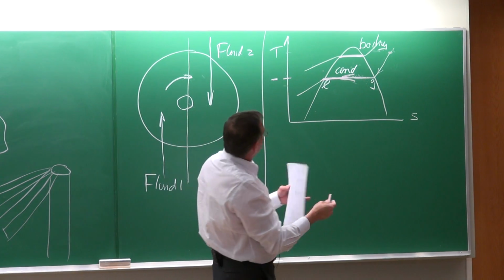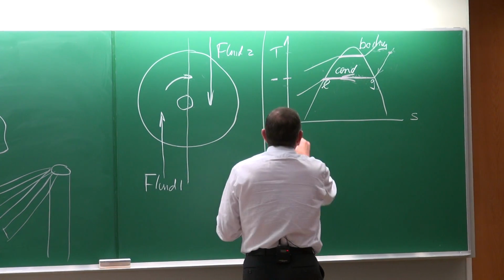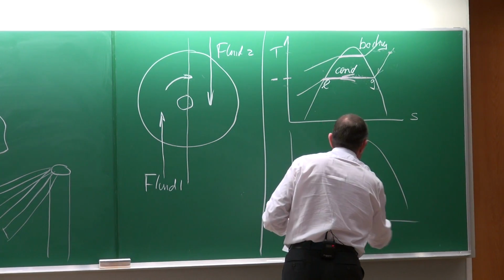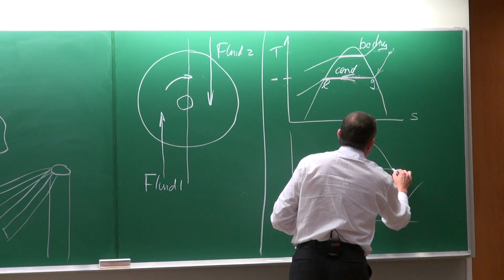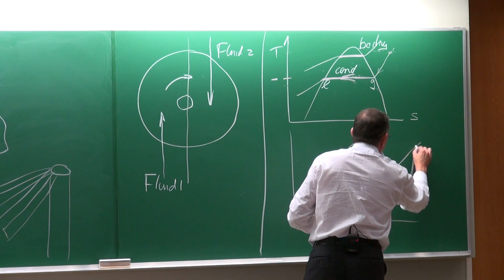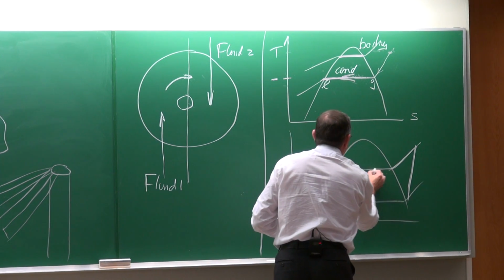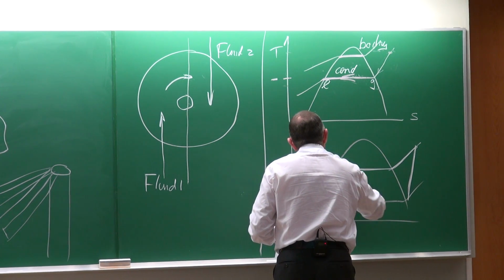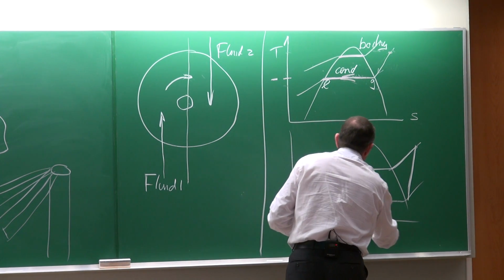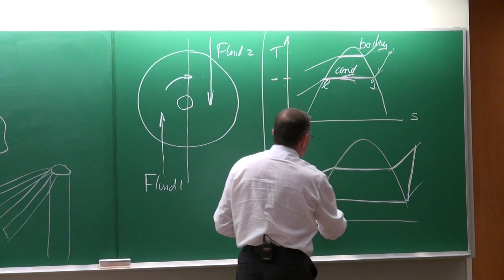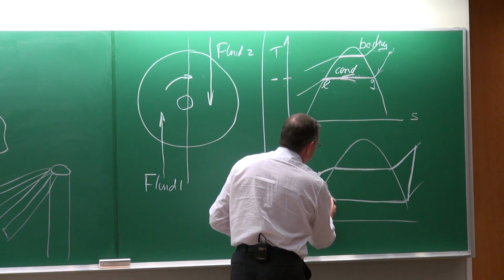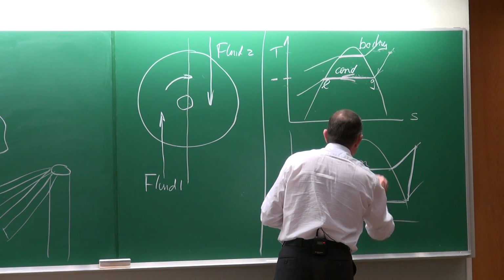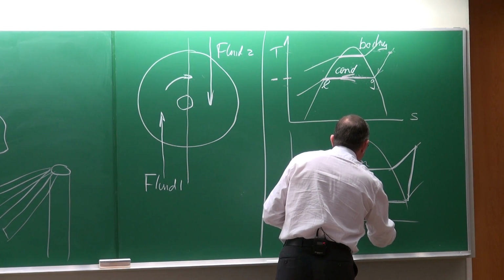If you've got a vapor compression system, again, typically like that, that's going to be the compressor, that's going to be your condenser, you're going to do a little bit of subcooling there, and then you're going to go through the expansion valve, and again, there you're going to have your condensation, there's going to be evaporation.